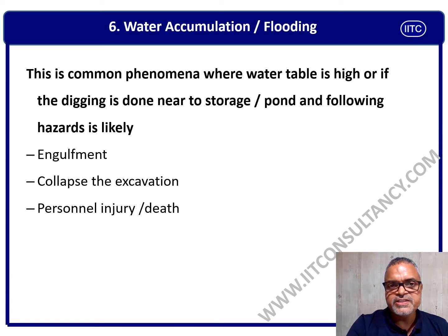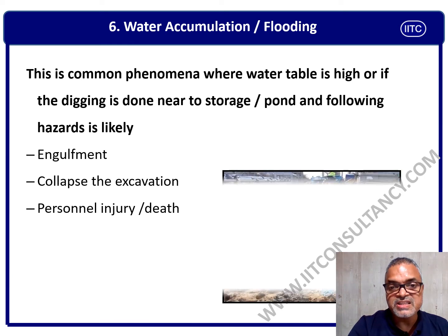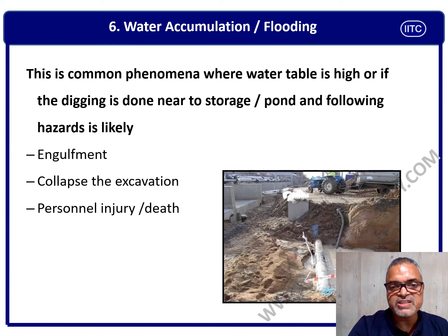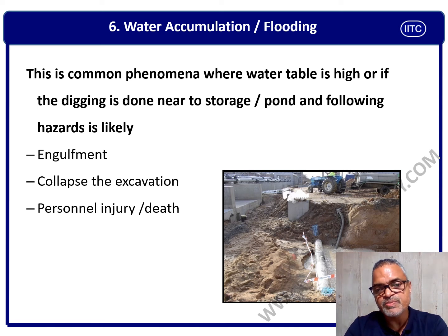Another hazard is water accumulation or flooding. This is a common phenomenon where the water table is very high, or if the digging is done near a storage tank, pond, or any other water body. The possible hazards are engulfment: people working inside the trench can get engulfed, the excavation can collapse, and personal injury or death is also possible. There were some cases in the past in Middle East countries. People were doing excavation, there was a landslide, there was a collapse of the excavation due to the water body, and people died.